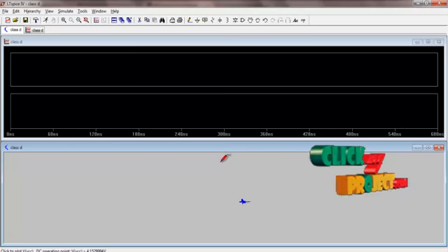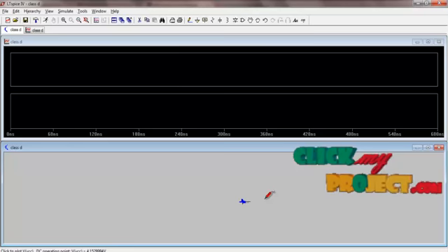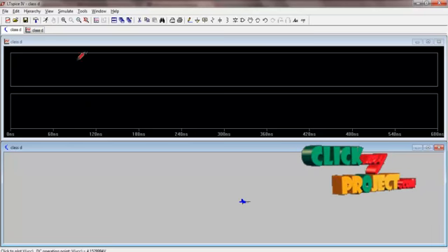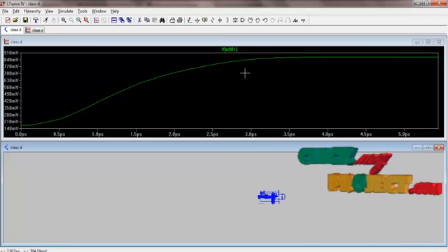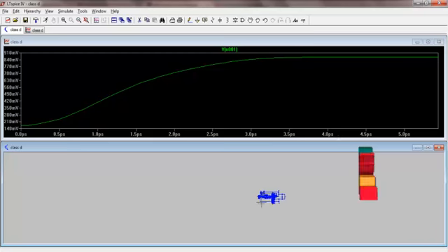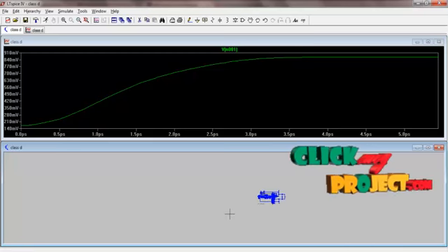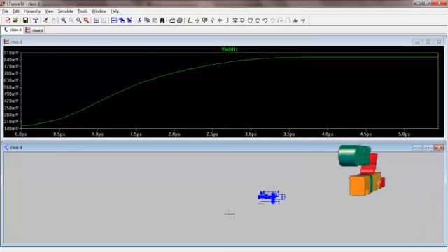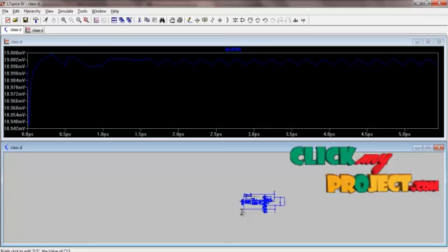Now we are going to see the input signal of our product. After running this design, we get a probe symbol in order to obtain the output waveform. This is the positive input of the PID compensator. Now we see the negative input of our PID compensator. In order to obtain the PID compensator negative voltage, we select a ground pin.